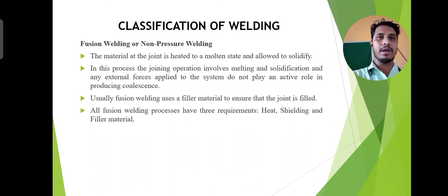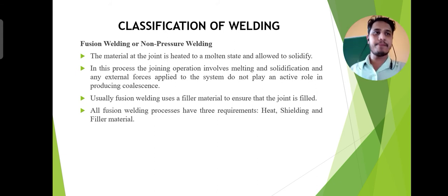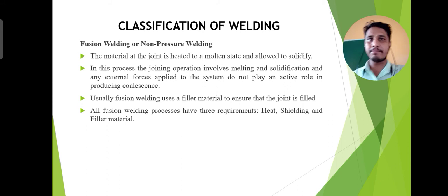And now this is the fusion welding. It is also known as non-pressure welding. The best example of a fusion welding process is the gas welding process. In this, I have told you that heat is obtained by the combustion of acetylene and oxygen mixture. And the material at the joint is heated to a molten state and allowed to solidify.